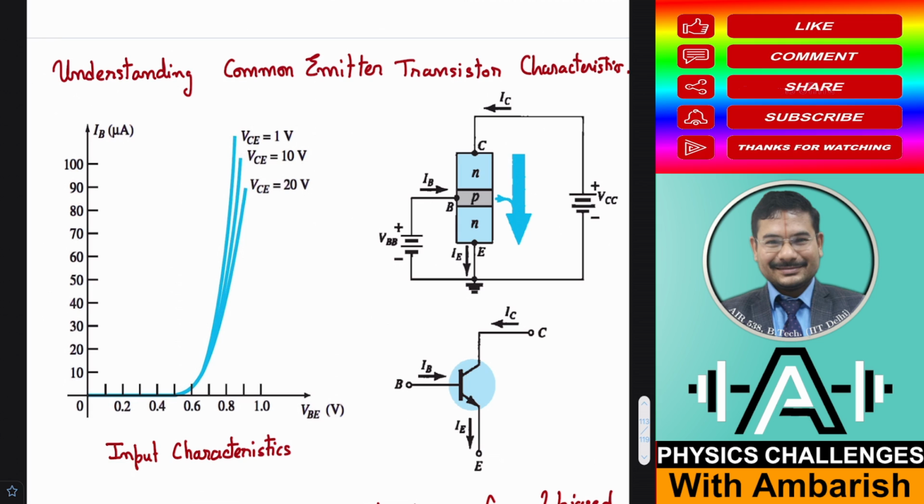And now what is the input characteristic curve? The input characteristic curve is between the base-emitter applied voltage and the base current. You can see here, if you draw the tangent over here, then that cuts somewhere around 0.7 volts, if you are operating somewhere over here. So what we are doing, we are changing the value of VCE, the collector-emitter battery values, and we are seeing how the base current varies with the base-emitter applied voltage.